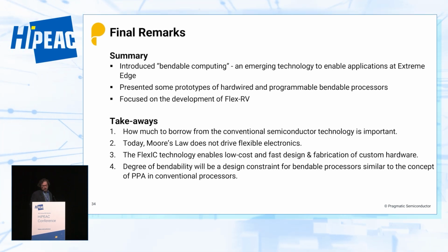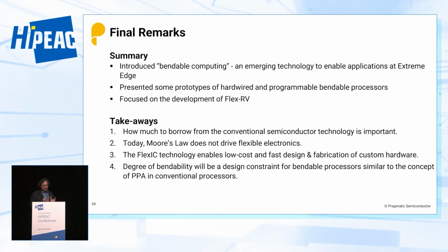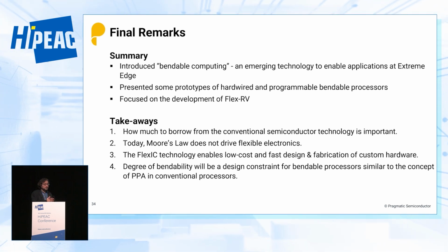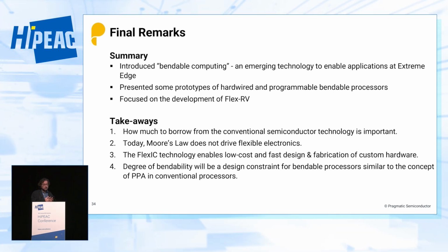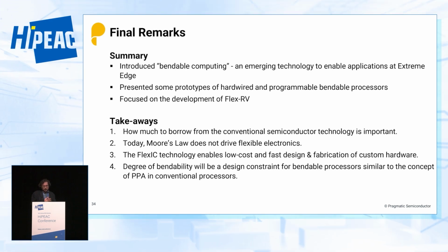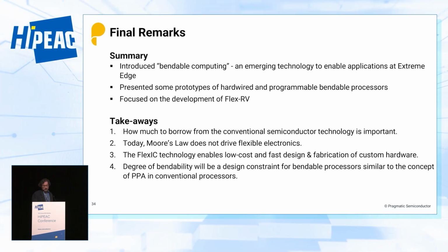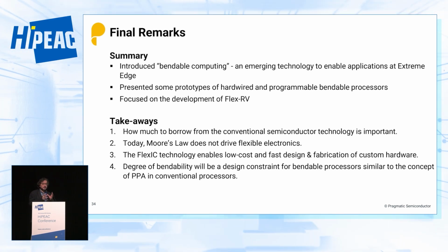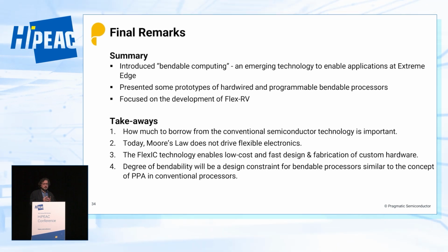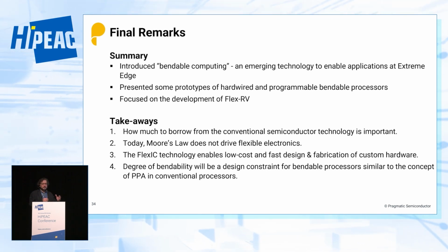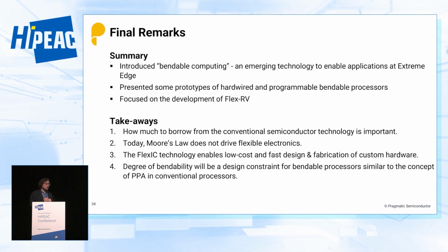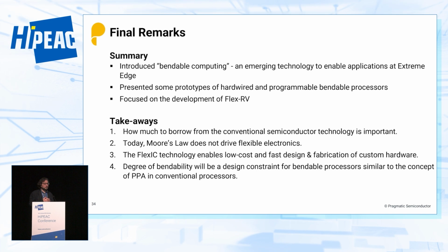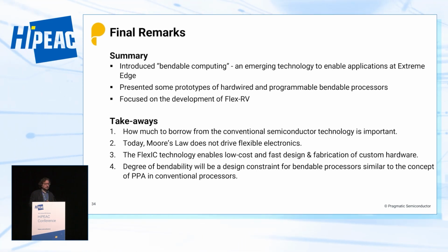One more thing I think I mentioned as well: FlexIC technology enables low-cost design and fabrication. This is unique, and I think it is very difficult for silicon, especially on the timing side. The last one is that the bendability is a unique feature, so we need to have bendability as a design constraint, similar to PPA, power, performance, and area, in the silicon world. When you're building a bendable processor, I think people need to add bendability as a design constraint and do more analysis. I think that is it. I hope I did it on time.